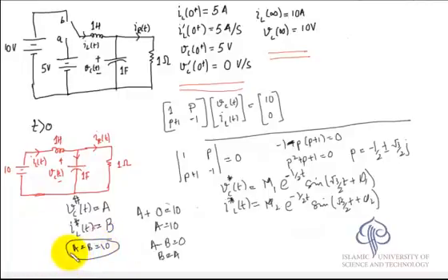And this is something that stays, as we have already discussed before. This is the forced response of the circuit, and the complementary function is the natural response of the circuit. This can also be obtained by looking at the circuit and finding the steady state values of the two variables that we are interested in, which we have already done, and we have already seen that the steady state values are going to be 10 for both IL and VC, and that is what we obtain here also.